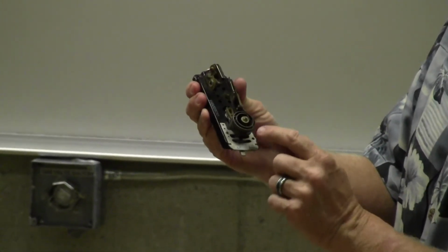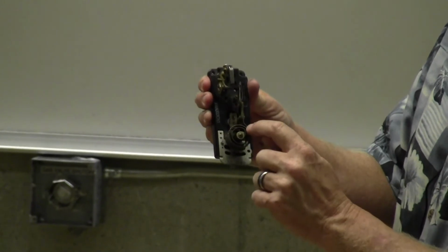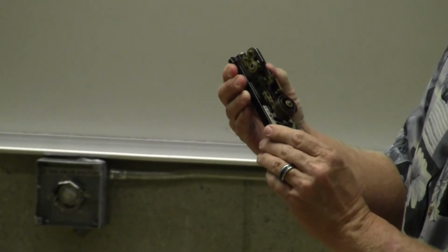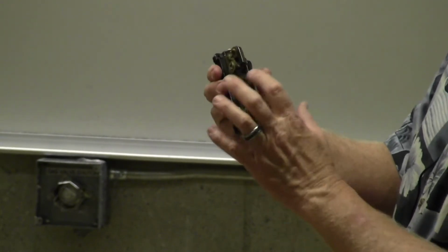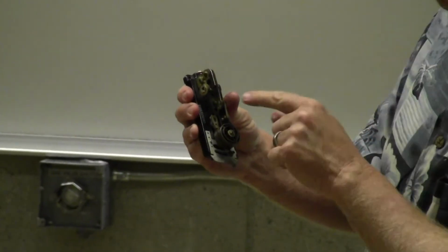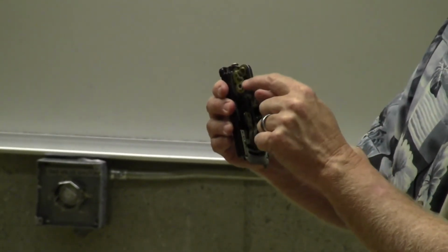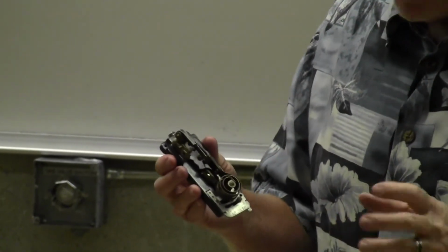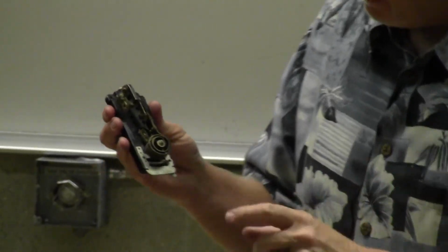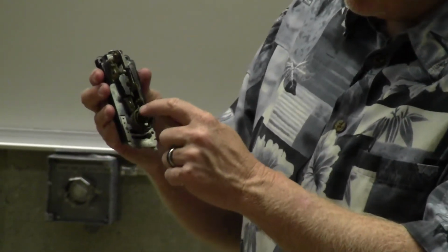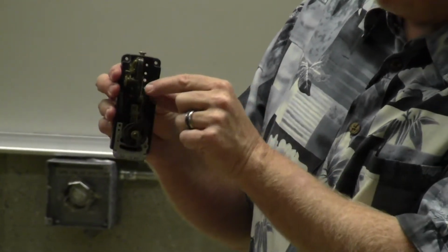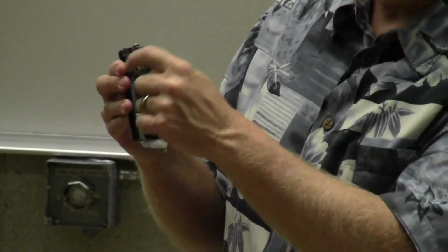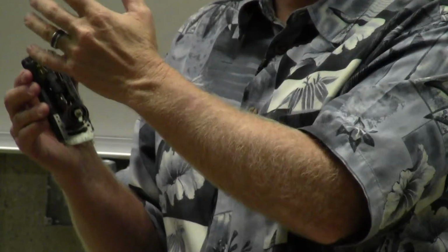But I can control this, and this little coiled up metal piece is a bimetal strip that if I then go over here, and it's kind of warm in the room today, so I can't quite touch it, but when I touch it, that makes electrical contact, and that then turns on the furnace. So what happens when it gets hot in this room is this unwinds and pulls this back like that. And now you don't have electricity going to your furnace, and your furnace is not on.